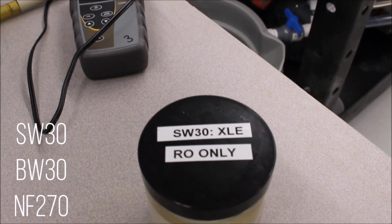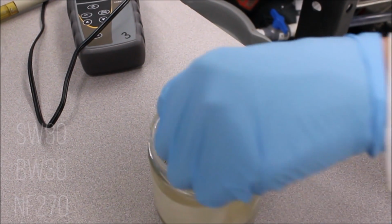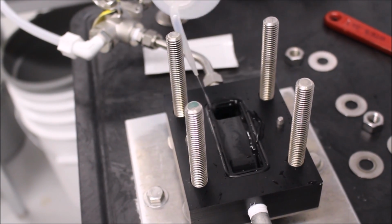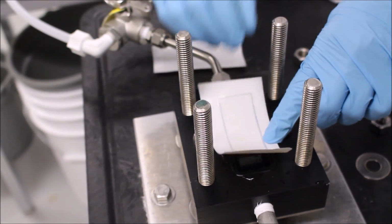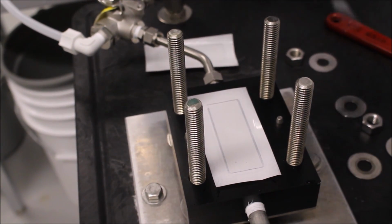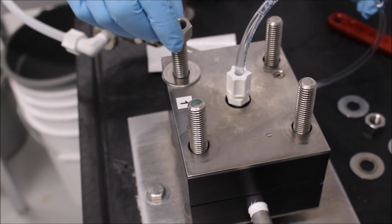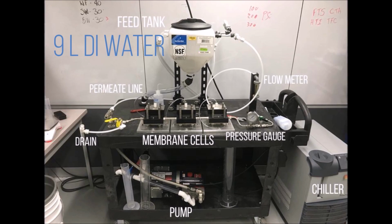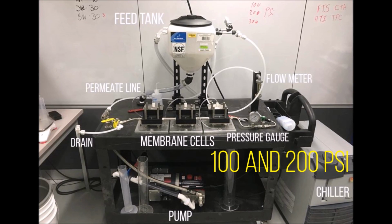For reverse osmosis, we will be testing 3 different membranes, SW30, BW30, and NF270. Carefully remove the membrane and determine the orientation. Wet the cell with deionized water before placing the membrane shiny side down. Place the top back on the cell along with the washers and nuts for a watertight seal. Fill the tank with 9 liters of distilled water and set to the desired flow rate. Again, we are varying pressure using 100 and 200 psi, which is set using the gauge.